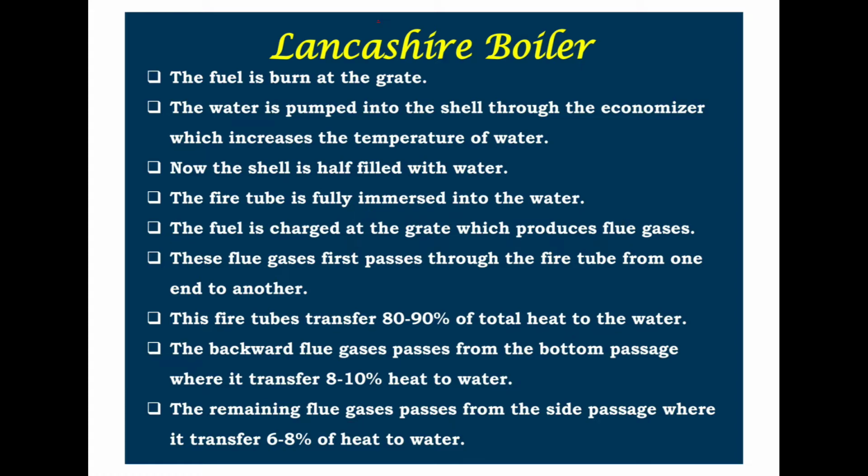Now the shell is half filled with water. The fire tube is fully immersed in the water. Fuel is charged at the grate, which produces the flue gases. These flue gases first pass through the fire tube from one end to another. These fire tubes transfer 80 to 90% of the total heat to the water.